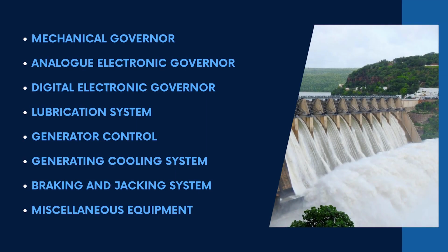Now, we have the second type of governor control that we call analog electronic governor. In electronic governor, hydraulic actuator speed sensing is by speed signal generators, that is also referred to as SSG. The signal is converted to proportional voltage signal and amplified in a magnetic amplifier. Electronic hydraulic transducer converts proportional signal to proportional pressure oil for servomotor operation. Feedback control is again by mechanical linkages. Control linkages, that is feedback, are mostly mechanical.